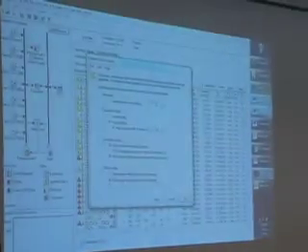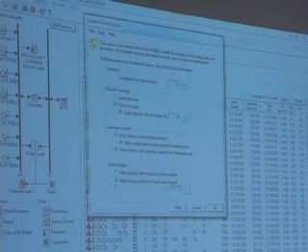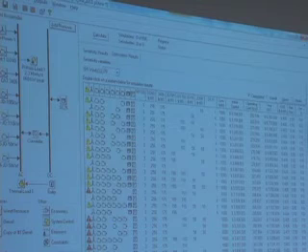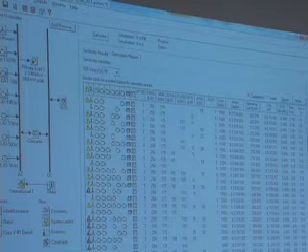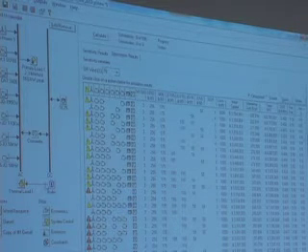Under system control here, it says allow excess electricity to serve the thermal load. So if we turn that off, it got rid of the dump load. So we have a thermal load. Homer sticks in a boiler. This isn't very interesting because it's just going to meet the thermal load with the boiler.